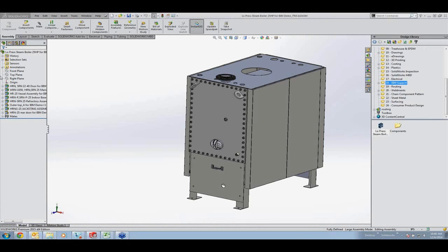But if I did want to update that plane to this new screen view here, I can edit the plane. In this case, it was plane 24, and update plane. The plane now updates to my current view, and I'm just going to turn off and turn on the section view here, and you see that updates the section view. Very powerful tools to help you design solid bodies.